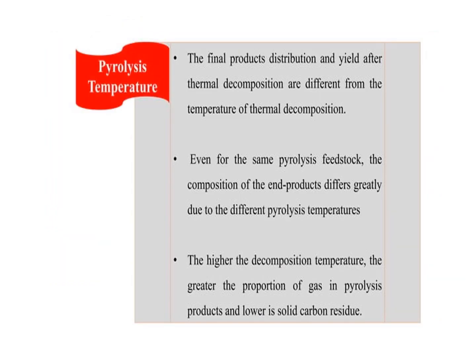Pyrolysis temperature. The final product distribution and yield after the thermal decomposition differ with the temperature of thermal decomposition. Even for the same pyrolysis feedstock, the composition of the end products differs greatly due to different pyrolysis temperatures. The higher the decomposition temperature, the greater the proportion of gas in the pyrolysis product and the lower the solid